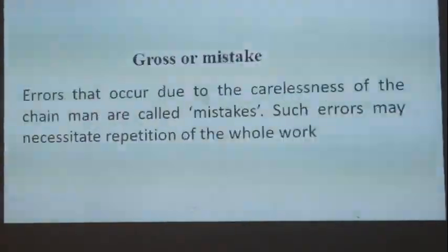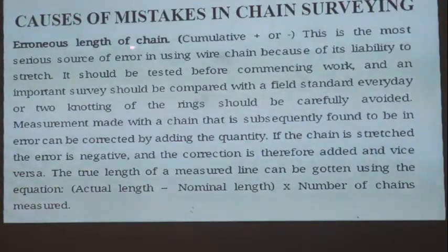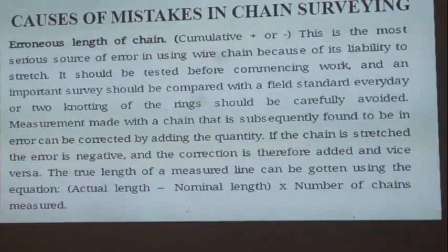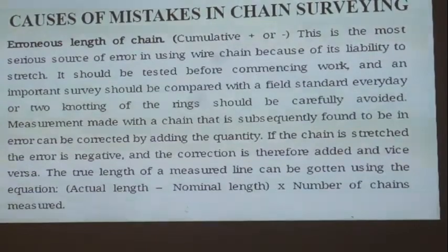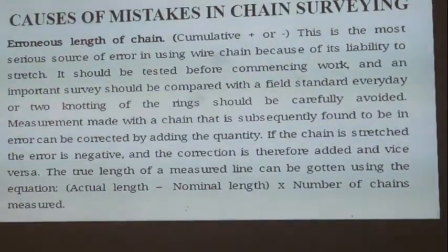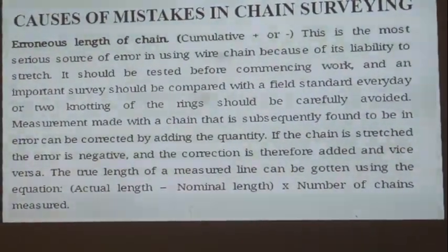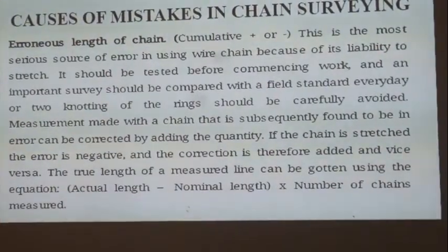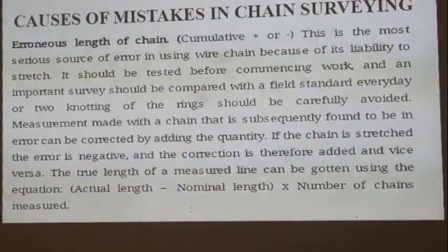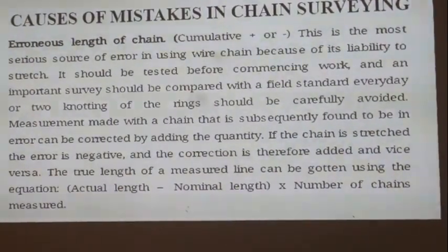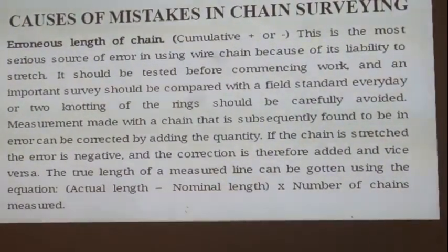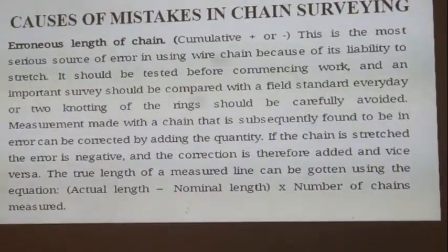I've told you erroneous length of chain. If they tell you the tape is 100 meters, check it against a standard base, which has been tested and proved to be known that it is true. With that, it will help you to know exactly if the tape you are using is right or is the correct value or not.